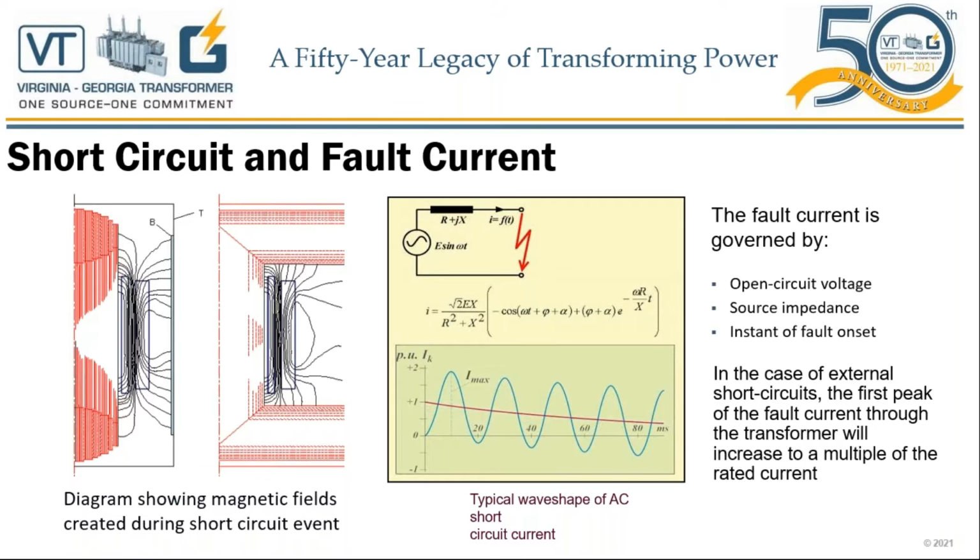And all of a sudden, this transformer is fully loaded, energizing what it needs to energize, and a large tree branch falls. It can either create a short between one power line and ground, or it may create, which is the case of the worst condition, a big, large, wet tree branch falling on top of the three-phase line. This is called the three-phase fault.